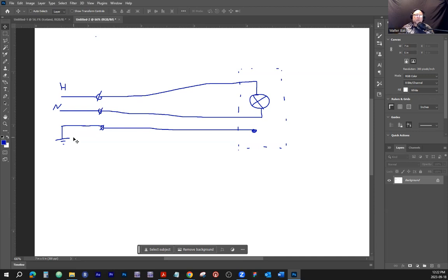And of course, what's going to happen if you have a circuit breaker in the electrical panel, it's going to sense too much current, it's going to open. It's going to disconnect the power to this circuit. So we have physically three conductors: hot, neutral, and the bonding or grounding conductor. But only two of those are considered to be current carrying conductors. So that's why